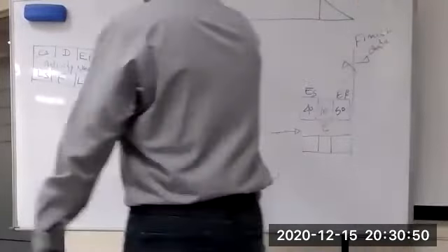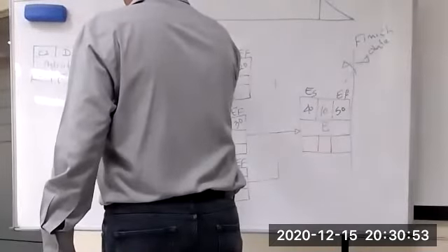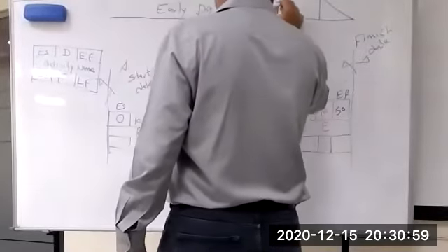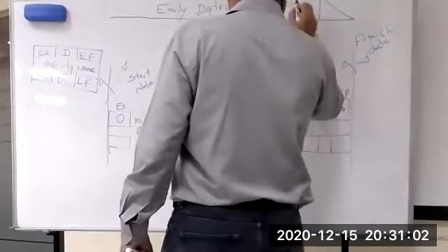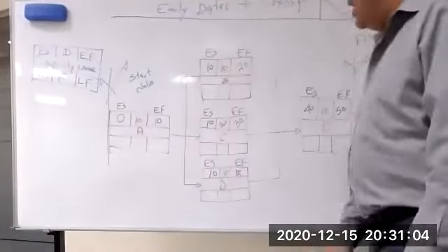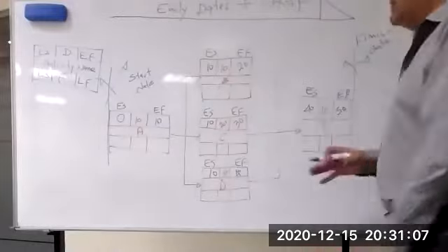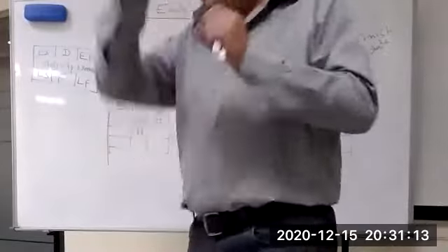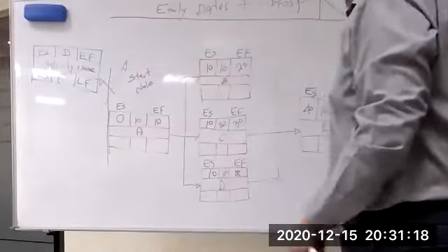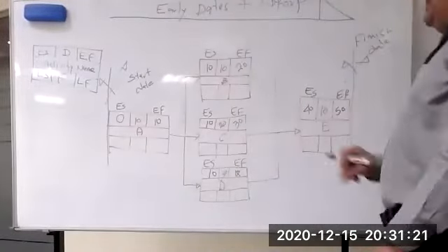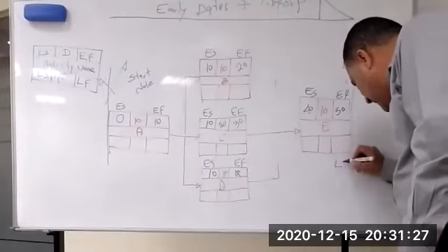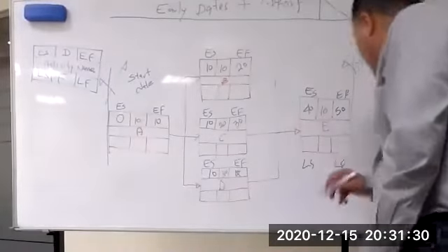What do I calculate now? The early dates plus the total duration for the project. So, all early dates and the total: 3 values. For each activity, the early start and the early finish, and in the end, the total duration for the project. For the last activity in your project, early finish equals late finish. This is late finish, late start. You add 50, 50.